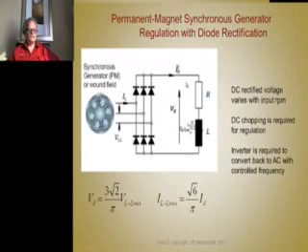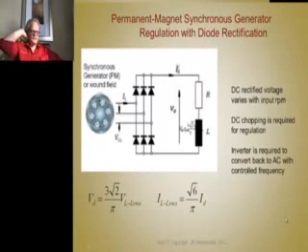But to regulate to some voltage lower than the rectified DC, you would use a DC chopper, use a transistor and turn it on and off, PWM. And these are the voltage and current equations for that.